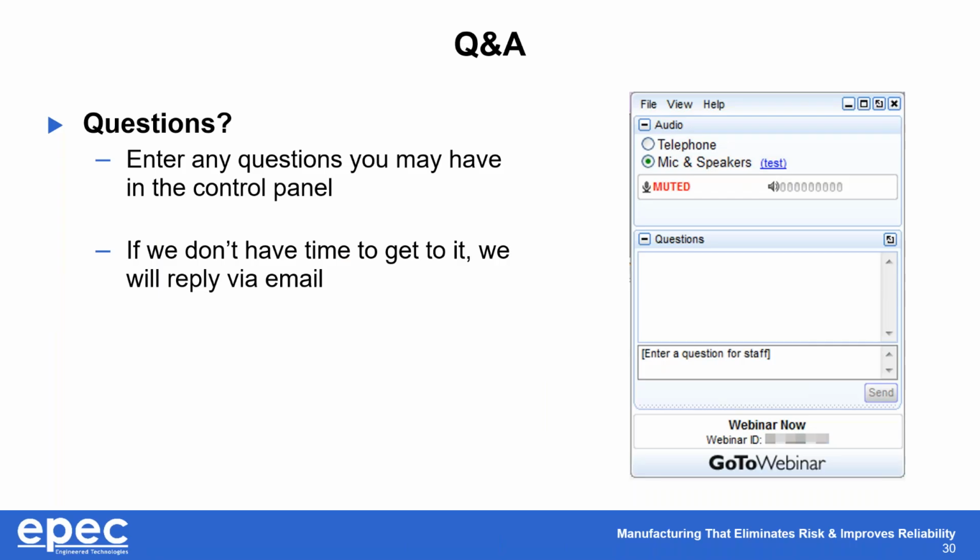So we may not have the tried and practiced stack ups that we've manufactured for those impedance values, but that doesn't stop us. We can fall back to the calculator just as easily and calculate it, and then at the end of our design test it to ensure impedance. So in that case, 85, I believe we have a stack up, but if you require a special impedance beyond that and we don't have it on hand, we can calculate it for you and then provide testing to ensure that we're within tolerance for those impedance values.